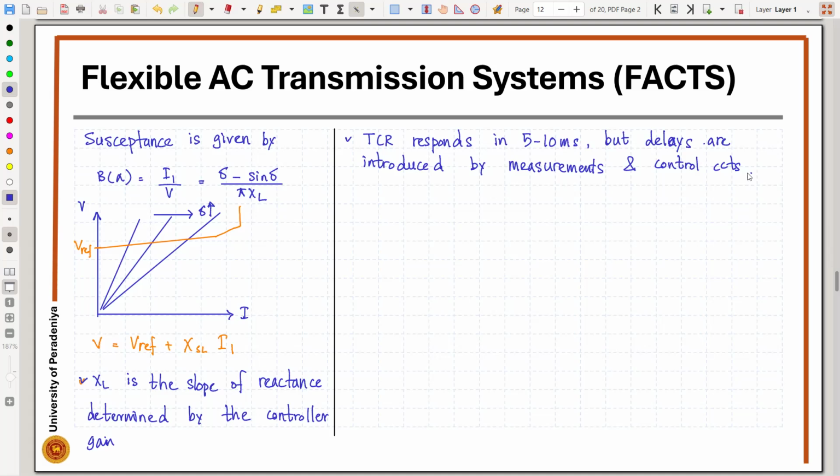We can place that at the end of the transmission line or the distribution line. So that will be absorbing the reactive power. Whatever reactive power is provided by the capacitive elements will be absorbed by the reactor that we place far away in the line. So this circuit will be helpful, especially in light loading conditions where you see a voltage rise.